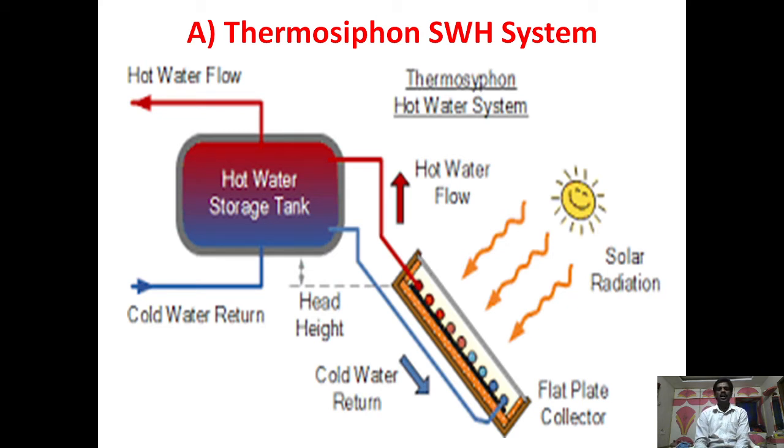process. The water that enters the flat plate collector is heated there by using the absorber plate. The absorber present inside the flat plate collector receives the solar energy incident on the collector, and whatever heat is received by the absorber heats the water that is carried through the conducting pipes.